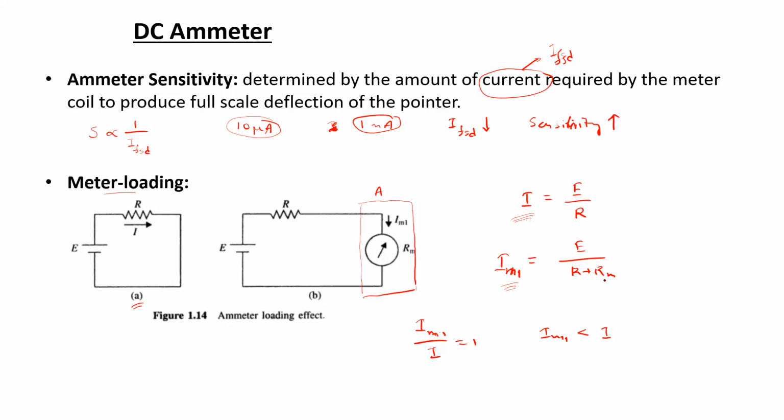Now adding the shunt resistance in forming the ammeter also serves as a solution to this in lowering the effective value of the resistance, or the equivalent resistance of the ammeter, as the shunt resistance is connected in parallel, and the parallel combination of the shunt resistance and the PMMC would eventually result in a smaller valued resistance compared to both the individual values of Rsh and Rm.